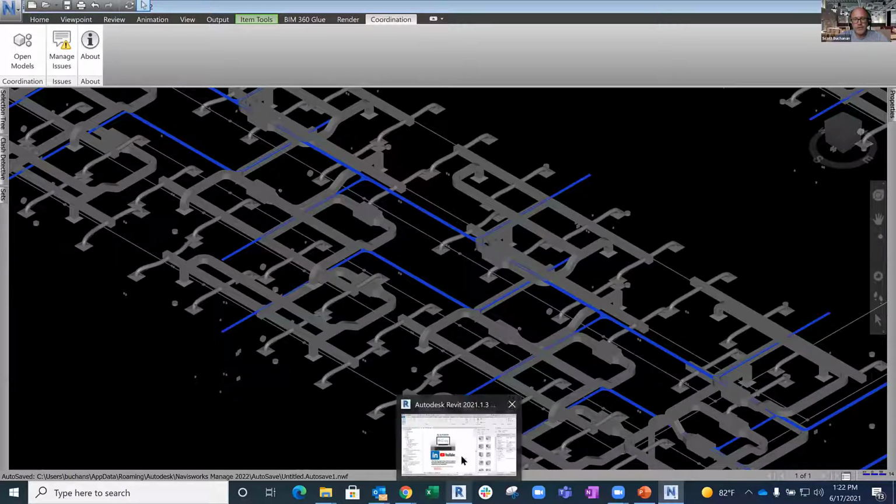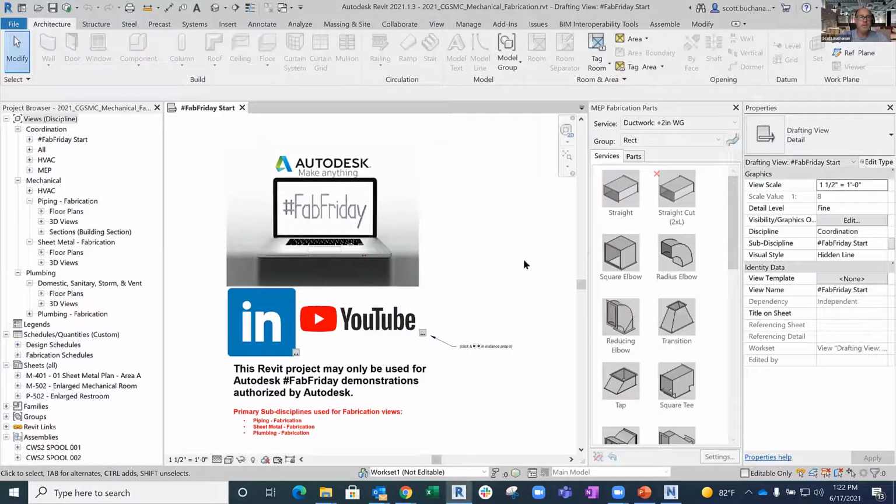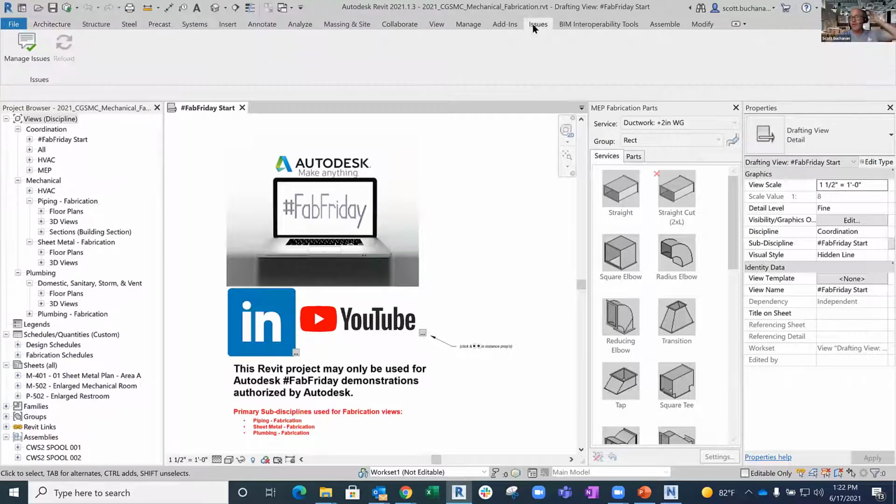And then on the Revit side of things, this actually gets installed from your desktop app. So if you go into your Autodesk desktop app, this will list there. Why the Navisworks one's not there, no idea, even though it's older. But install that. It's going to work on Revit 20, 21, and 22 for us.